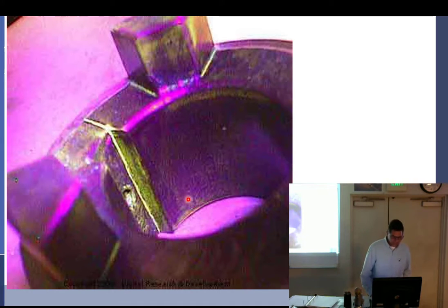Okay, so I kind of like this picture here for a couple reasons. One, is this a crack? No. How do you know? That's leakage. Well, it could be. The one on the right looks like an indication. The one on the left looks like flux leakage. When I see that, I can't just dismiss it. I'm going to watch its behavior. One, if there's a puddle here, I'll try and blow the puddle away. Two, I'm going to see what it does on the other side. If it starts making a corner, going down a little bit, I've got a problem.